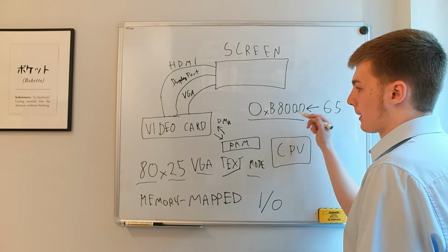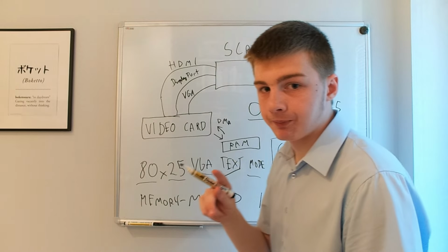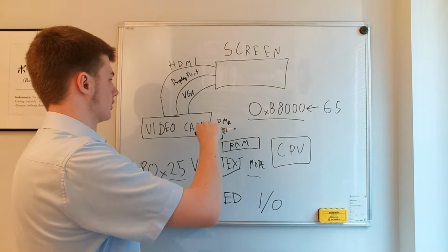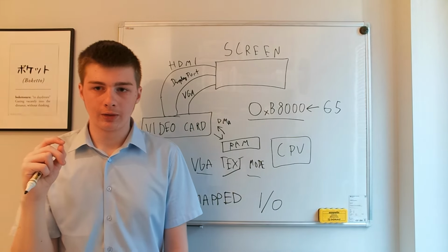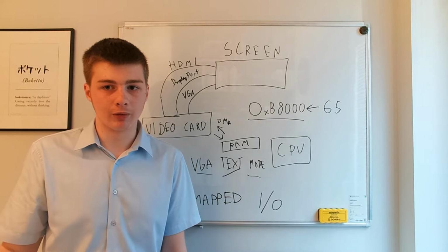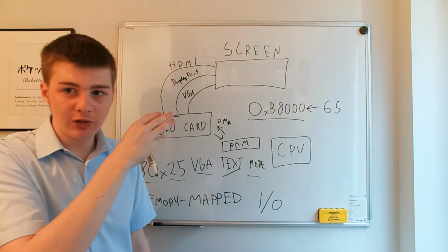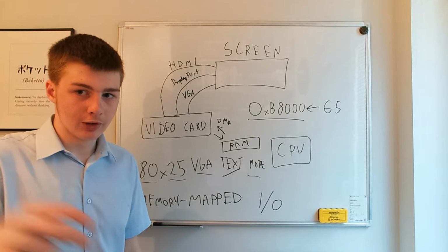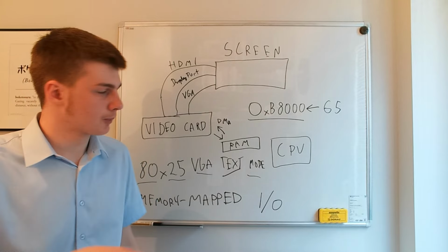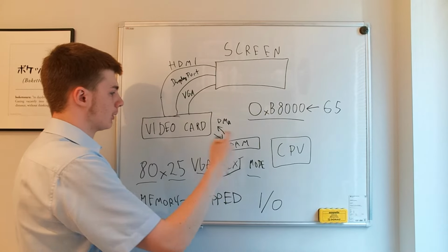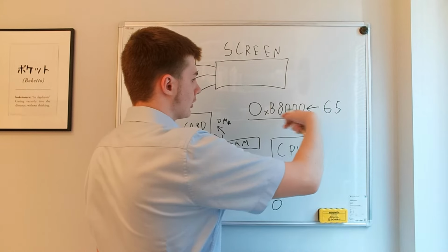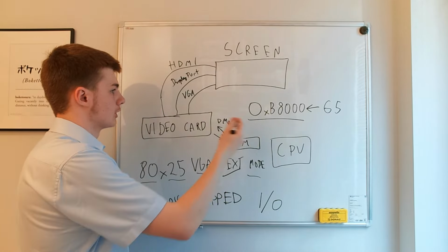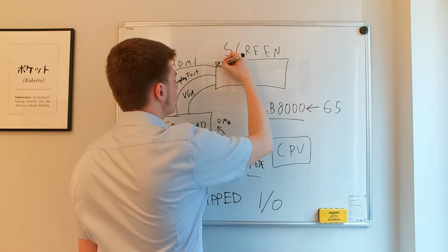So you place this value at the address, your card reads this buffer and says, okay, we have the value 65. Now I'm going to turn this whole buffer into electrical signals. The video card will have a ROM, and some of those regions, for example, store fonts. So it says, I know that I'm in a text mode, and I know that this is 65, so it corresponds to this set of pixels, and it's here on the screen, so it's going to display the letter.